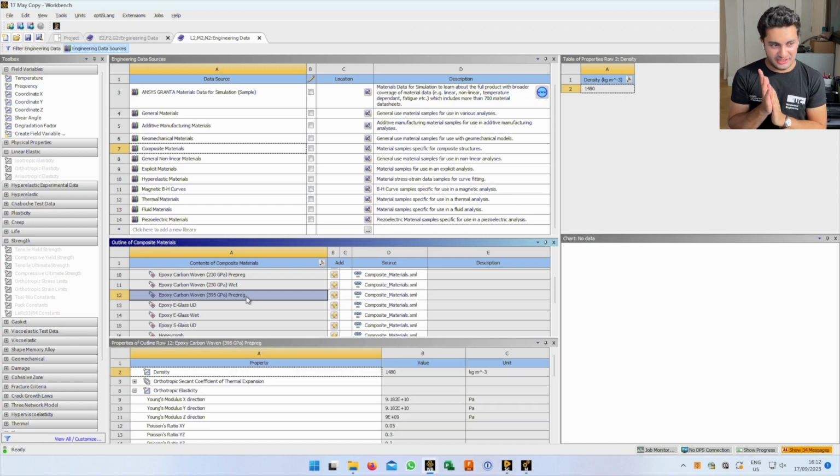And then it's not just about the orientations, but also how you layer the different layups of carbon fibre. So you could have one layer of unidirectional, you could have one layer of woven, and then a layer of unidirectional, and then another layer of woven on top of that, and that is going to behave far differently to if we just had 3 layers of woven.